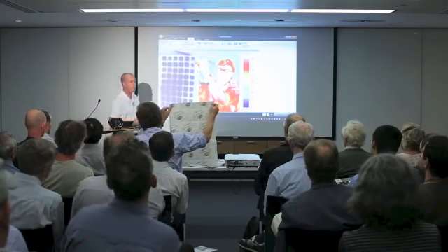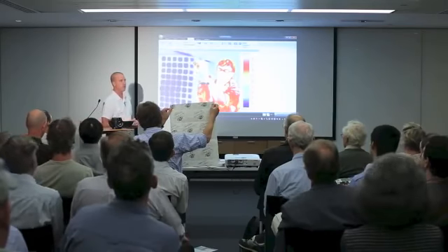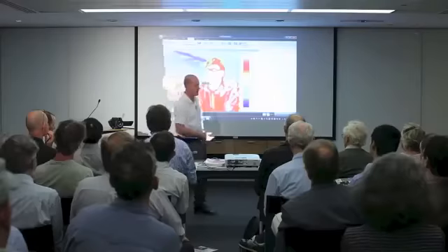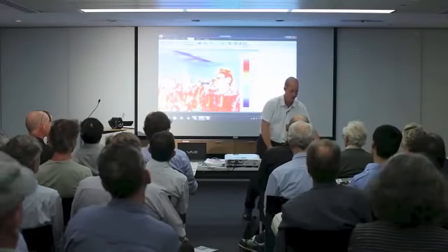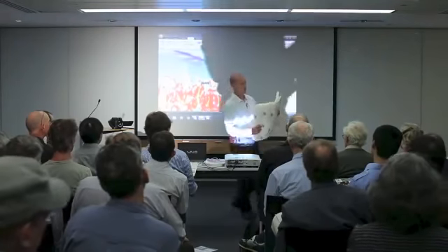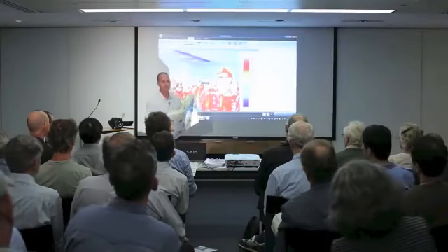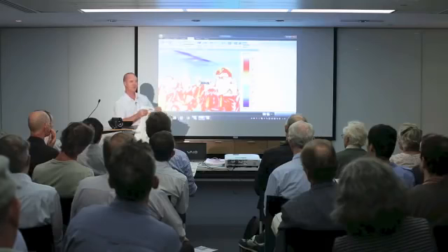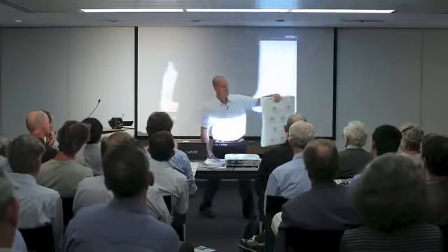Now that mat was in Melbourne this morning on a concrete floor where it actually refroze itself. So it refroze itself using the night air. And that's the most clever thing about phase change material, is you've got free energy. Because the energy that's stored in here is just the energy that we let go of last night when it cooled off. So we're kind of like Robin Hood. We steal from the rich and give to the poor. So we steal the heat, steal the cold out of the night and give it back in the day. Or in the cooler months, we steal the heat out of the day and give it back in the night. It's quite logical when you think about it.